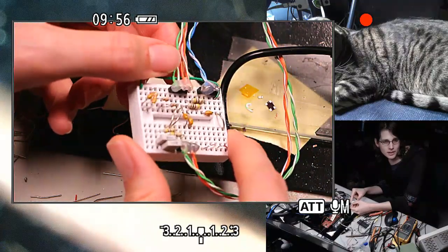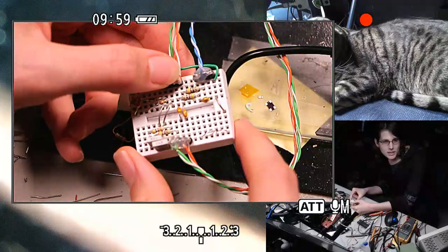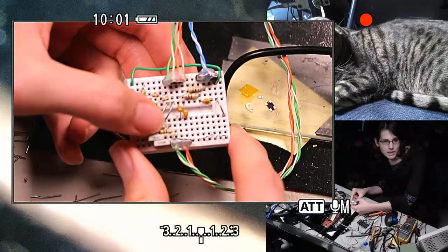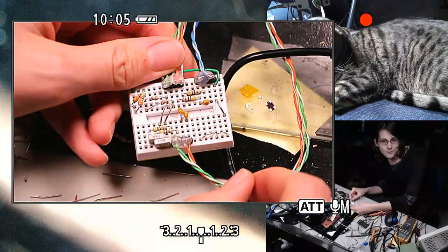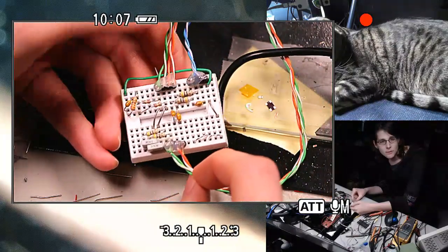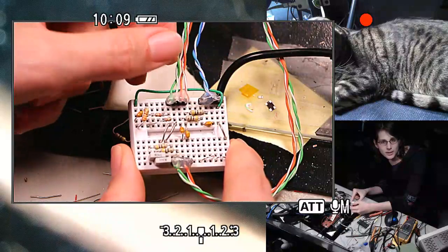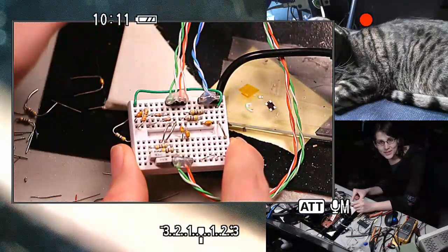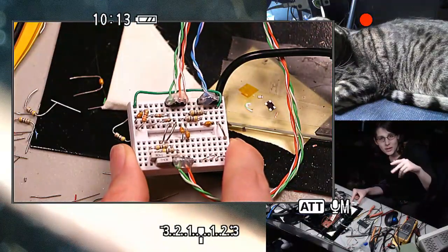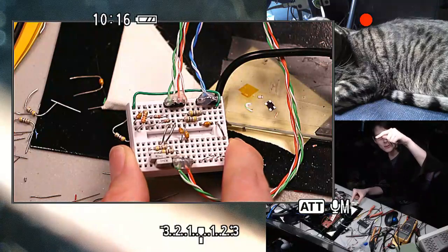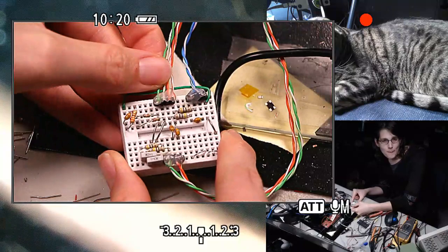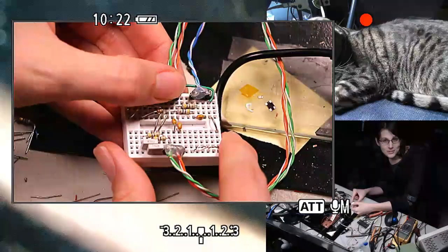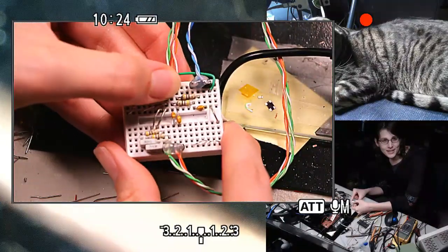Also, another thing that I've been having issues with here is not with this particular circuit layout, but I think with different capacitor values. I was having trouble with, I think it was the signal coming from the ENC28J60's transmitter, seemed to oscillate. So it wouldn't just go from 0 to 1, but it would actually oscillate from 0 to 1 and then oscillate back down from 1 to 0. Which also makes me wonder what the driver circuit in the ENC28J60 looks like.